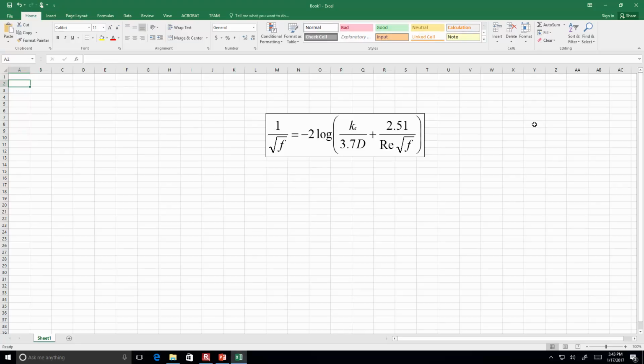All right. So from the initial given information and the calculations I did before, we had the K sub s in millimeters was 0.15. We had a diameter of the pipe in millimeters. That is 136 from what was given previously. And then the Reynolds number that we calculated on the whiteboard was 1.87 times 10 to the 6th.